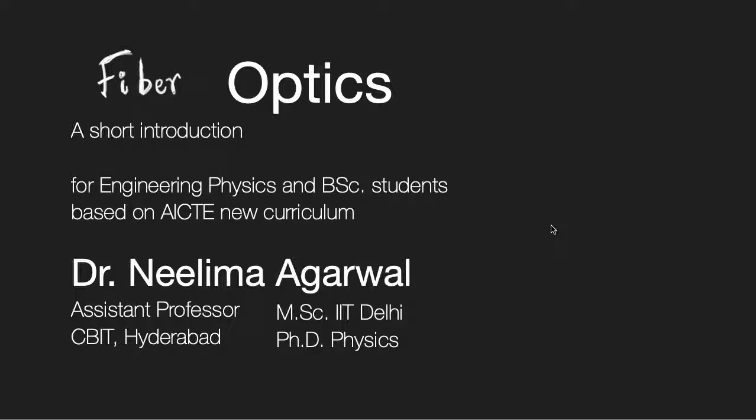Then, based on the number of modes, we classified the fibers as single mode and multimode fibers, where single mode supports only one mode as its thickness was very small, and multimode fibers support a large number of modes due to more thickness of the fiber. Now we can again classify the fibers by combining these two classifications.